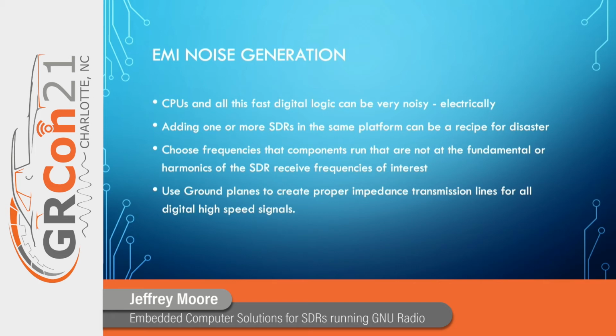So you've got to be very careful in your design of how you lay down the digital logic, where you locate it with respect to the SDRs and how the SDRs are shielded, etc. We use ground planes and proper impedance transmission lines for all high-speed signals, and that's just the tip of the iceberg. There's no time to go into that here, but it's just a very, very important criteria.